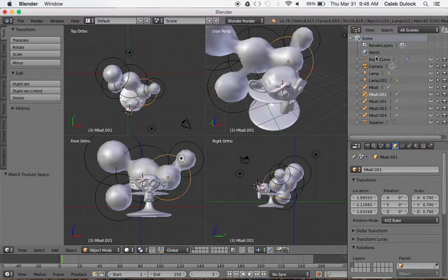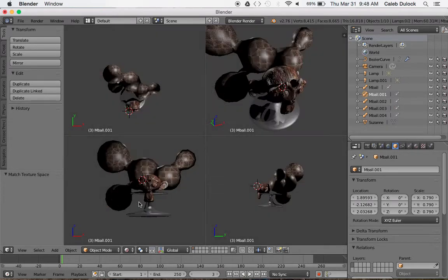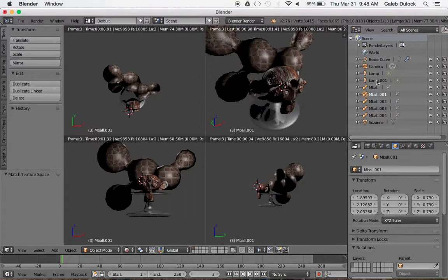Okay, so we check our scene to make sure that nothing is strangely out of place, that we don't have any strange models or forms or elements floating in our scene. The other thing that we'll want to check is to make sure that our textures are showing properly on our objects. So for that, I'll switch back to rendered, to review how my objects each look. Now, the one thing I recommend when looking at objects inside of Blender is sometimes it's good to use the isolation mode button or shortcut key so that you can review one object by itself in your scene at a time.